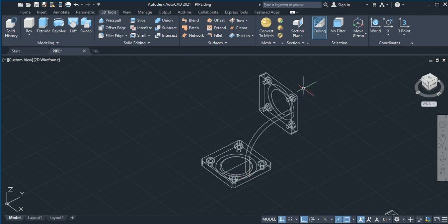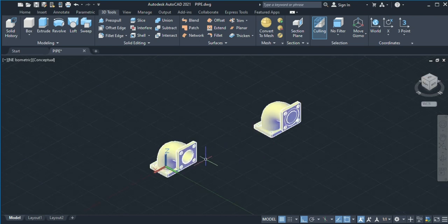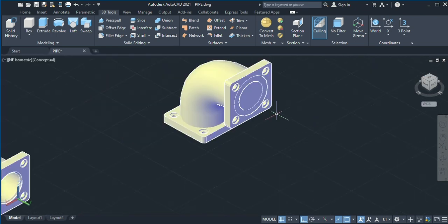So we have this one. Already put up the square. We call it a block at the start and end of the part. But the thing is, as you can see, if we do conceptual, the pipe itself is not hollow. This one is another example, but for this one, the pipe is not a hollow pipe. So what you can do is subtract on this pipe. Just subtract on this pipe, then we subtract and make it a hollow.